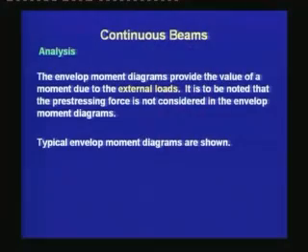If the beam is of uniform cross section or the spans are more or less of similar length and the loading is more or less uniform throughout the length of the beam, then the moment coefficients can be used, which simplifies the calculations of the design moments at the span and the support regions. From the design moments, we can develop the envelope moment diagram.